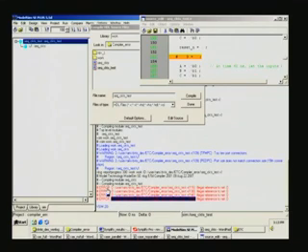The error gives the path name of the file up to this, and it gives the line number here, and this is some 153 line number, and that is precisely what it is here in the open file. And it is reporting there because D has been referenced, it has been forced to 1 here in the test bench, and because it is illegally declared as wire instead of reg, so it is promptly reporting. After the line number it says illegal reference to net, then colon D. D is the signal under question.